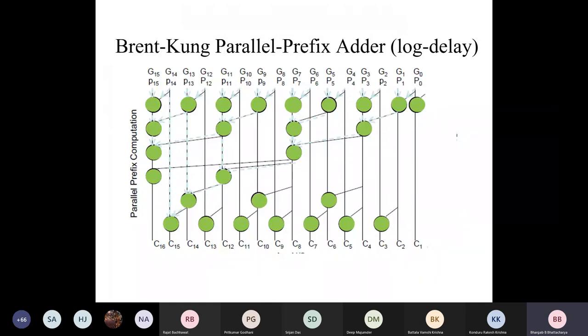So it achieves logarithmic delay, it achieves logarithmic fan out, and the logarithmic cost for the total adder, I mean the complete adder. How is it that? Okay, in the previous case, this arithmetic operation was just a logical AND operation, right? Here, this is now a little bit more complex logic module. So this implements this carry recurrence function. Again, as you can see, this is a simple logic, right? It needs only one AND gate and one OR gate, right?